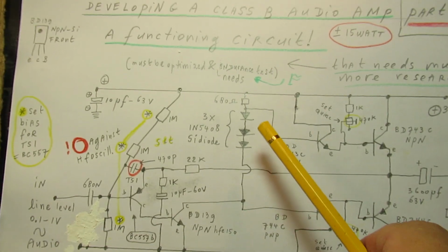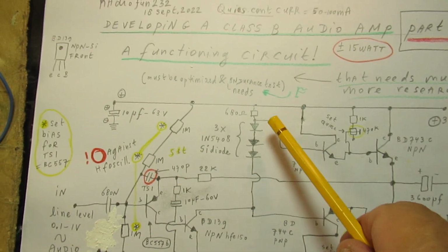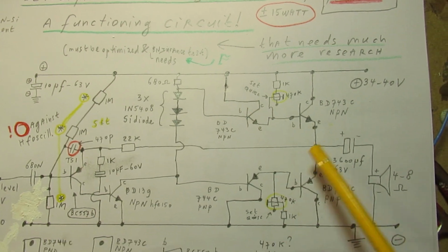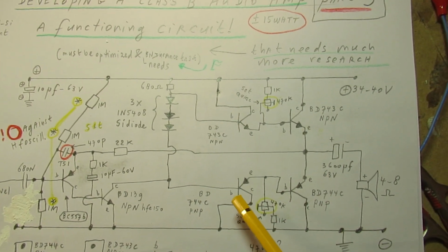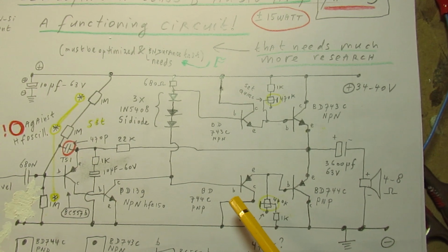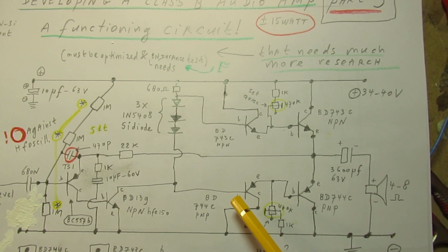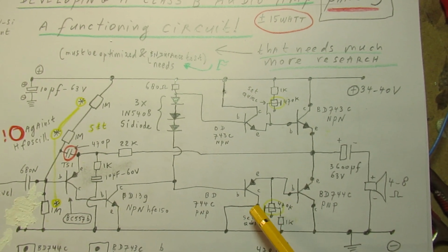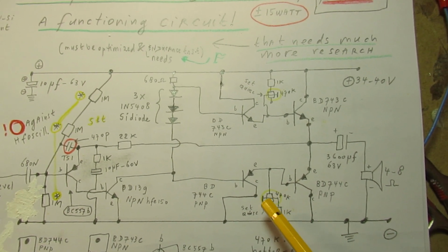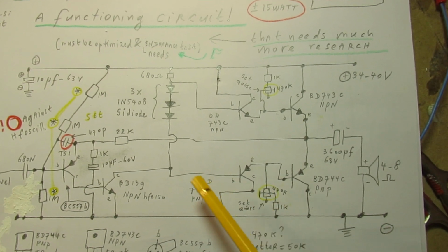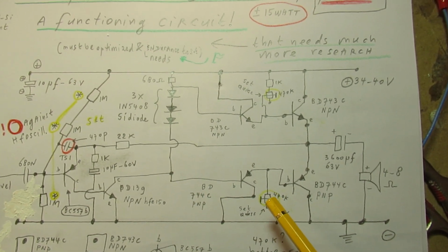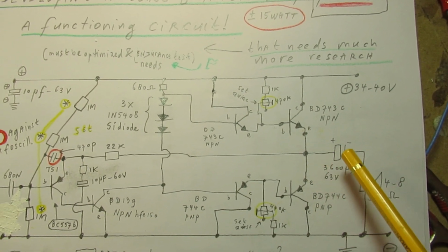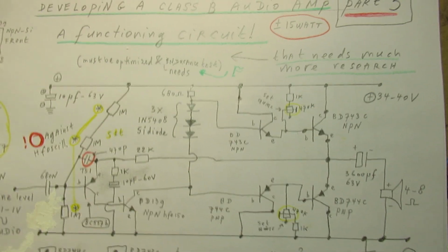These diodes set a certain voltage drop, and because we have here a Darlington now, each silicon transistor needs approximately 0.7 to 0.8 volts to work properly. Two of them approximately 1.4 volts and somewhat higher, so to be driven out properly to get a signal out here via the end capacitor to the loudspeaker.